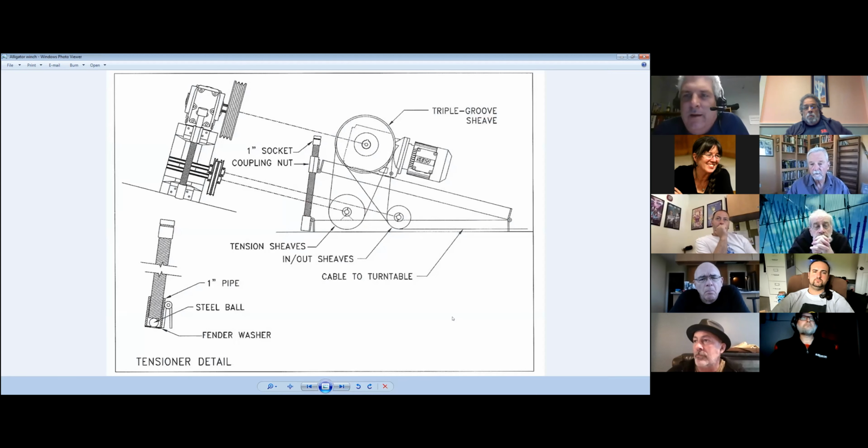We would buy a big endless loop cable that we would have someone long splice for us, wrap around the perimeter of the turntable and reeve through those friction sheaves. For many years, that was our go-to turntable drive, and it worked exceedingly well, with no problem. So there's definitely a time and a place for it. There's no question. The magic words, however, are long splice.